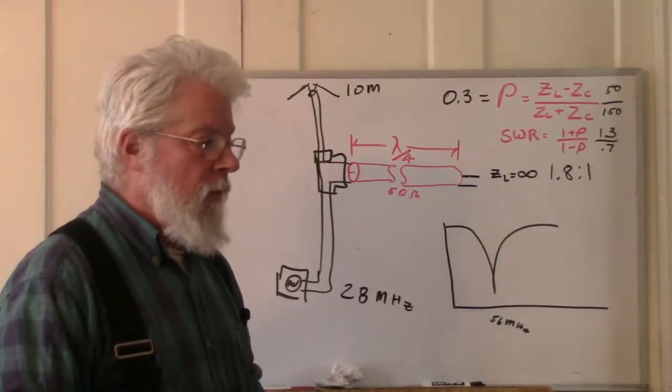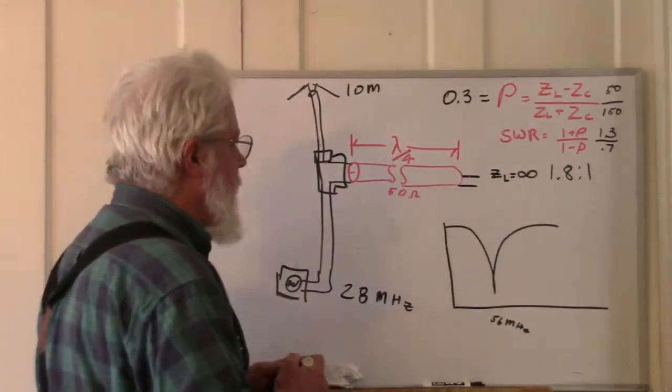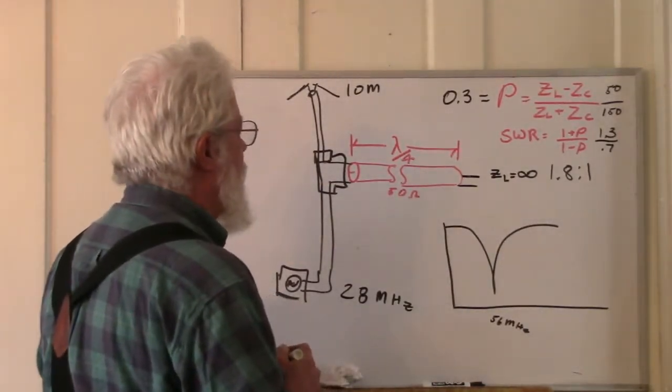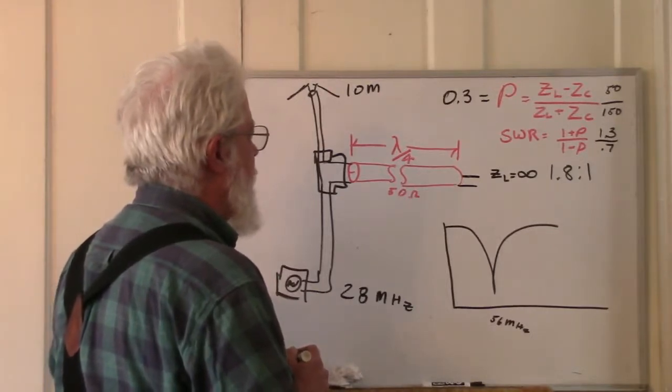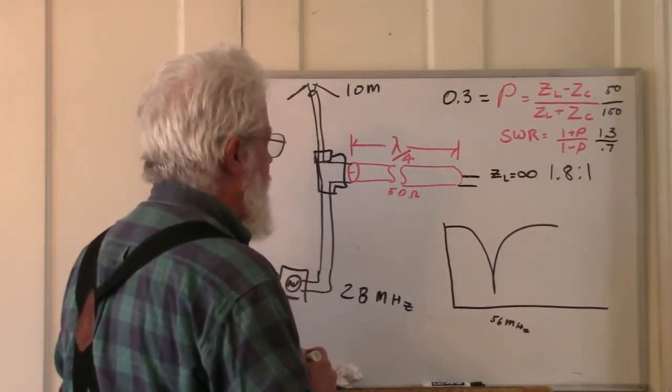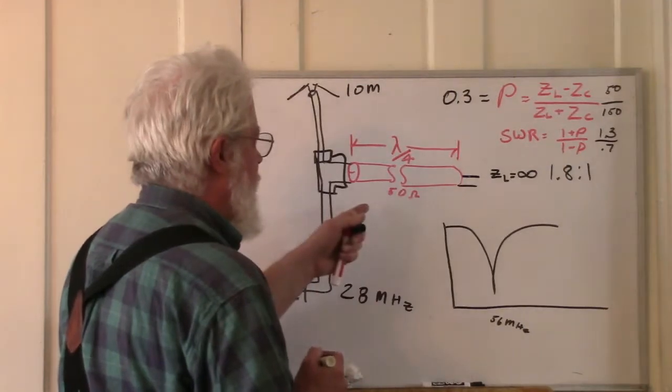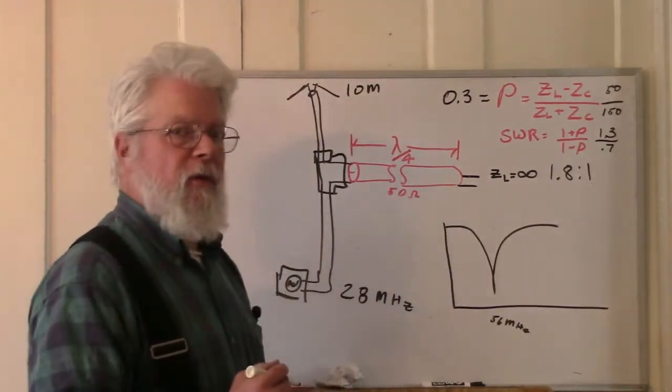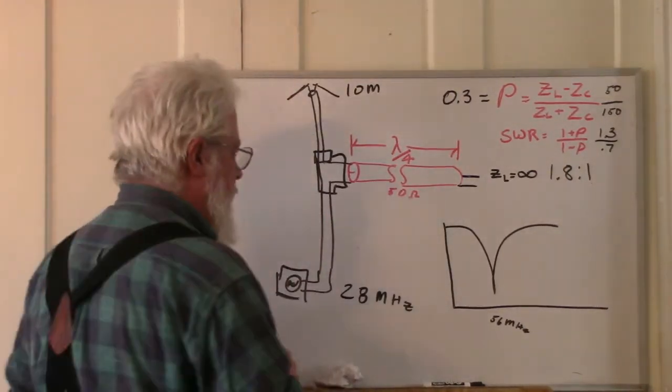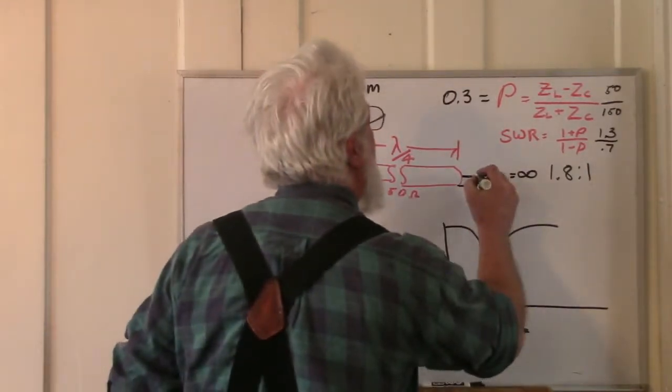Oh, what if I make it a quarter wave at 28 megahertz? I'll make it twice as long. And I'll make this a dead short.